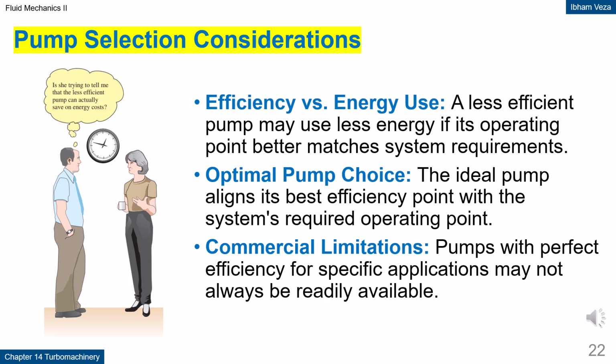Pump selection considerations. Pump selection is not determined only by the maximum efficiency listed in the catalog. In many cases, a slightly less efficient pump may consume less energy if its operating point better matches the system requirement.